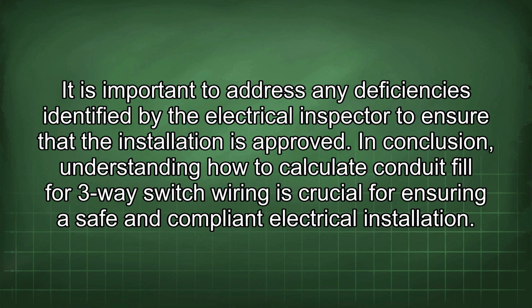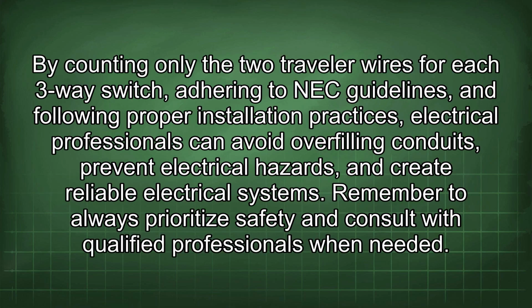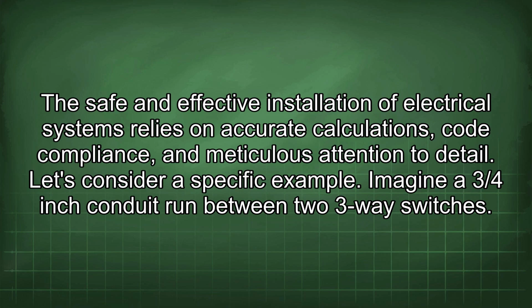In conclusion, understanding how to calculate conduit fill for three-way switch wiring is crucial for ensuring a safe and compliant electrical installation. By counting only the 2 traveler wires for each three-way switch, adhering to NEC guidelines, and following proper installation practices, electrical professionals can avoid overfilling conduits, prevent electrical hazards, and create reliable electrical systems. Remember to always prioritize safety and consult with qualified professionals when needed. The safe and effective installation of electrical systems relies on accurate calculations, code compliance, and meticulous attention to detail.